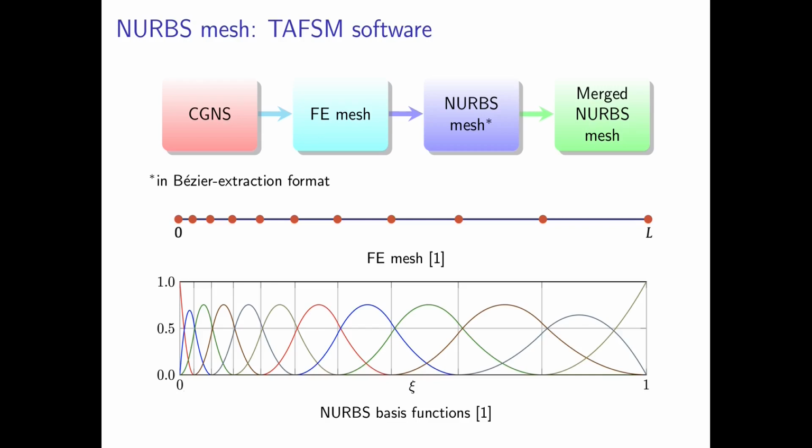To properly address the projections, we first need to discuss NURBS basis functions, because NURBS basis functions describe the relation between the finite element and NURBS meshes. Here we see an illustration of the NURBS basis functions corresponding to the above one-dimensional finite element mesh. The question is, how do we construct these basis functions?